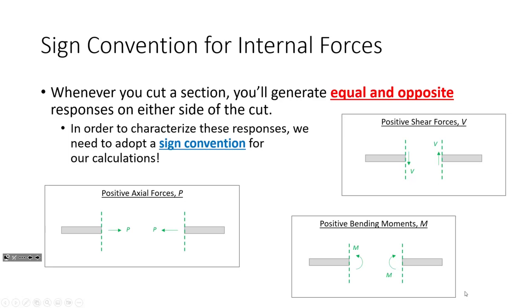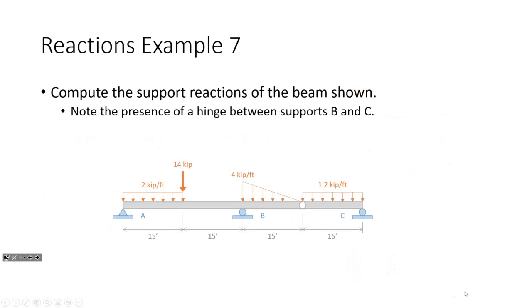When you're designing buildings, you're designing beams and columns, and they just want to know what the compressive force is in the column. Whereas general purpose finite element codes like MASTAN, or some of the higher level ones like Abaqus or ANSYS, will typically assume tension is positive. So you just need to be consistent with what you're doing. Again, that'll become more important a little later.